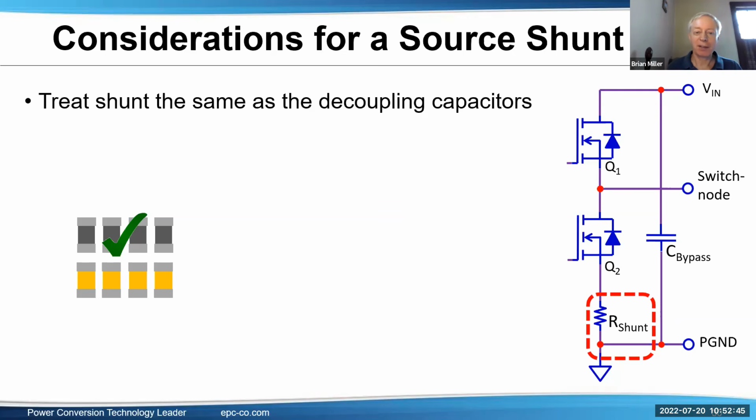The best way is to start with a good layout, just have them close together. Beyond that, pick the resistor to minimize the ringing. Look at it in both directions. But err a little bit on the side of a slight bit of ringing won't be bad.